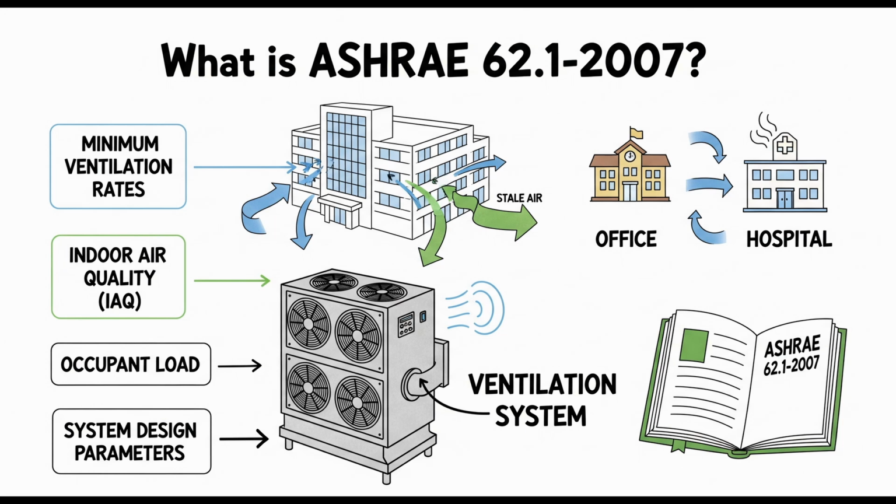The perceived air quality goal, assessed by occupants, usually relating to odor and irritation, is still part of it. Then you use engineering methods, often mass balance analysis. Basically tracking the pollutant: how much comes in, how much goes out, how much is generated inside, how much is removed by ventilation or air cleaning, to figure out what ventilation rate or what other control measures you need to meet your target concentrations and acceptability goal. Appendix D gives some equations.